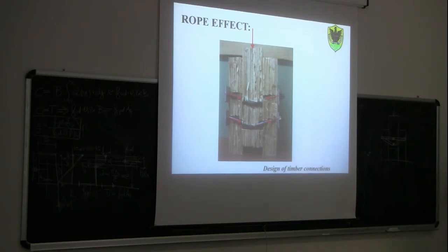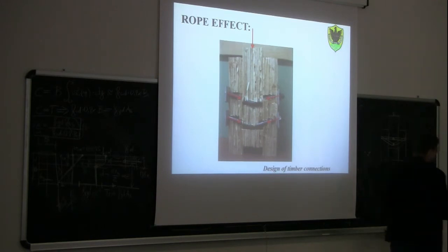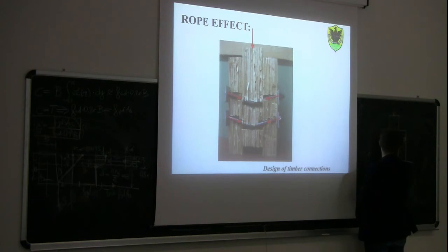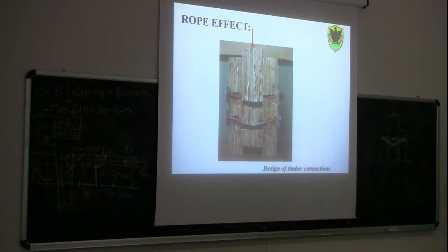So either the dowel elongates itself, or the easiest thing that may happen in this case is that the head of the dowel will keep its total length constant, and the head of the dowel will go inside here. So in the end, the length will be the same, but the dowel is going to move inside in this case. Okay?